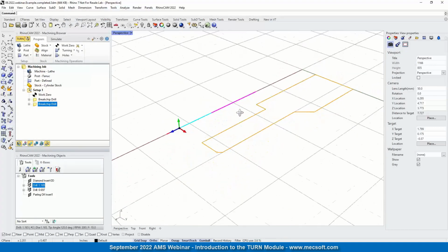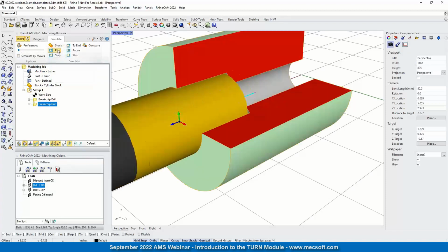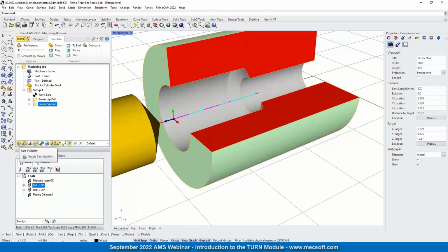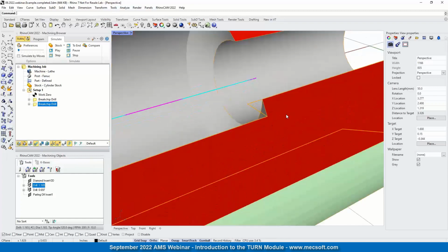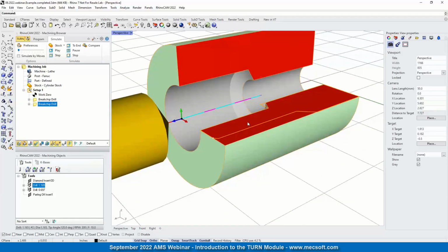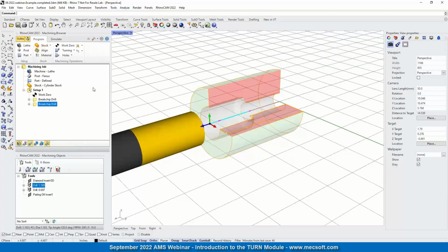So let's go ahead and generate that. Here's our second drilling tool path, and we'll simulate that. There's our roughing for the ID. If you turn the part on, you'll see that we got pretty much all the material out on both faces here on the inner side. Make sure that you're acceptable with this angle here from the tool as we went past the point for depth. So there's our roughing.